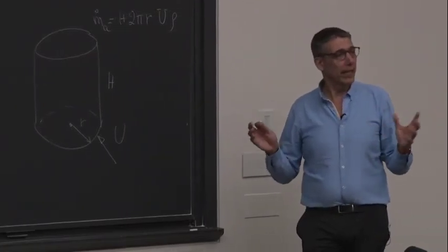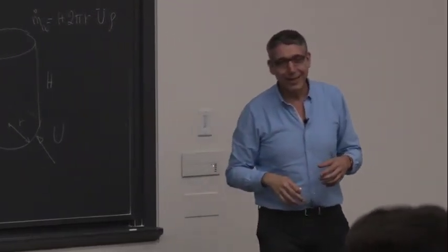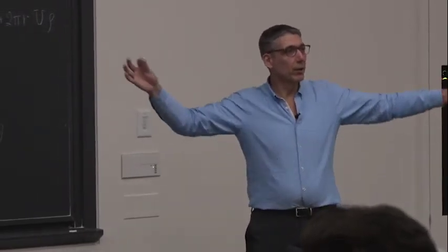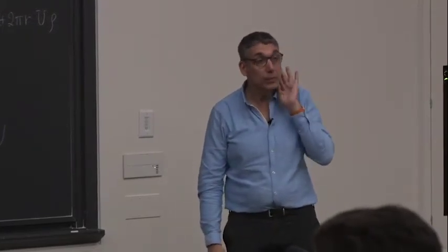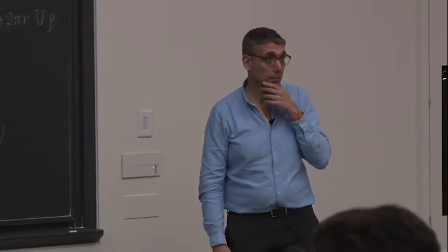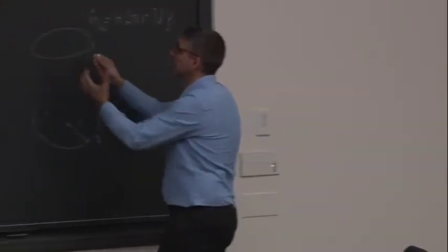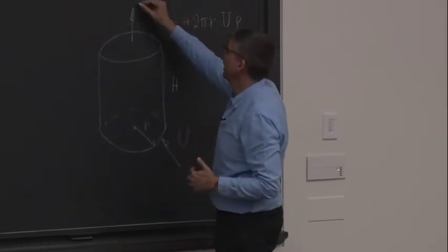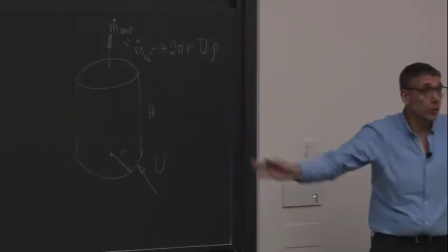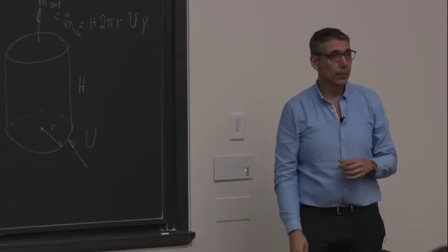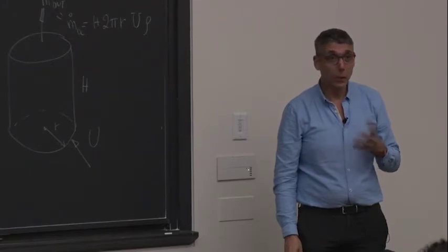No, no, but I mean, would this number here that I just created, in general terms, represent the amount of air that is entering that cylinder? You've defined a control volume for your problem. And all that air that comes in there is going to go out in here. So this M a is going to be equal to this M out. So it's the same. No? It comes in through the cylinder, it gets out. Are we all happy with that? Nobody's upset at me?